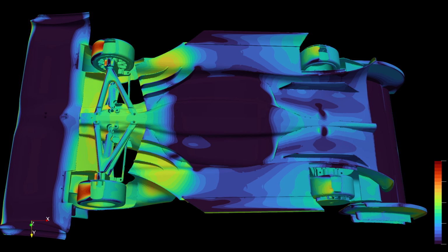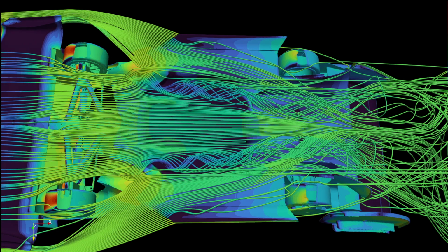They help to energize the air coming into the diffuser by creating a nice set of 3 smaller vortices, which almost instantly join together to form a pair of counter-rotating vortices on each side of the diffuser. These vortices keep the boundary layer thinner at the throat and help promote flow attachment and decrease the sensitivity of the diffuser as the car pitches and yaws.